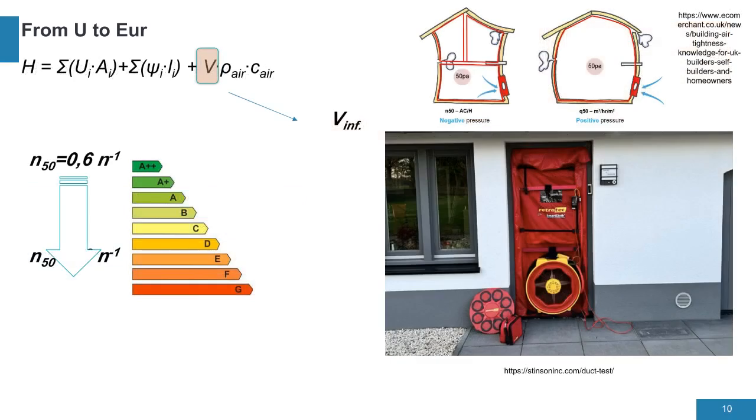In addition to natural ventilation, which is intended and designed to exist in the building, there is also unwanted air circulation called infiltration. Cold air infiltration into a building occurs through unintentional gaps, cracks, and openings in the building envelope. Common areas for cold air infiltration include zones around windows and doors, improperly sealed sills, gaps and cracks where walls meet the foundation or roof, and any holes in walls, floors, or ceilings for plumbing pipes, electrical wiring, or ductwork. These are all potential sources of air leaks.